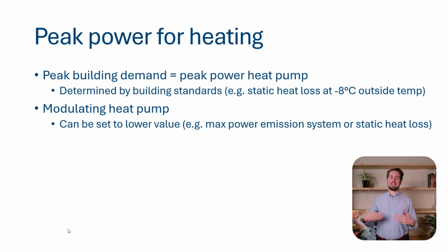So oversizing a heat pump is also causing oversized bore fields. So that's something to keep in mind if you're working with modulating heat pumps.